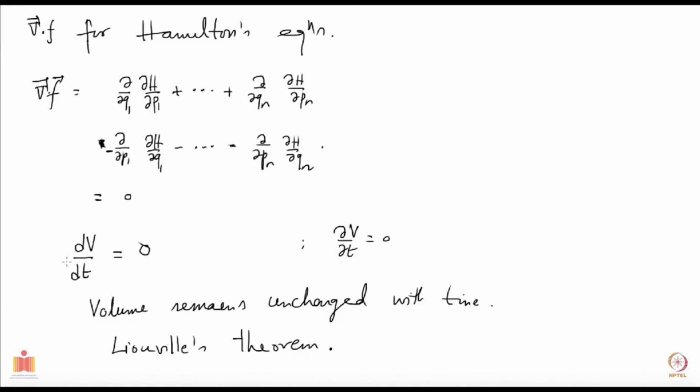So you are really moving together with all those points as they move, and you are then asking whether the volume changes or not. But if you are just looking at the partial derivative, then you are staying put at one place and just looking at time changing, and then of course the volume will be changing there. It will be reducing, for example. So what happens there locally is different from what happens when you are flowing with the points. We are talking about this piece, not just time passing at the same place.